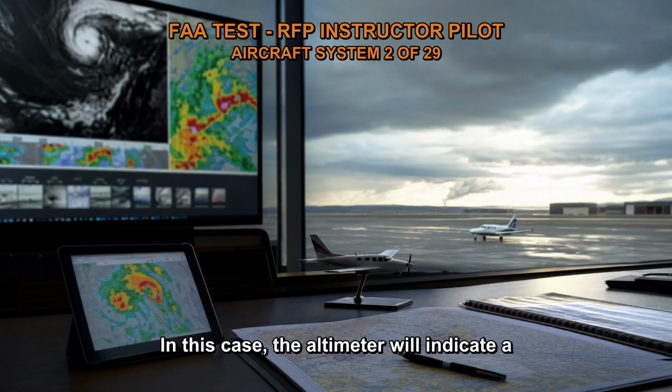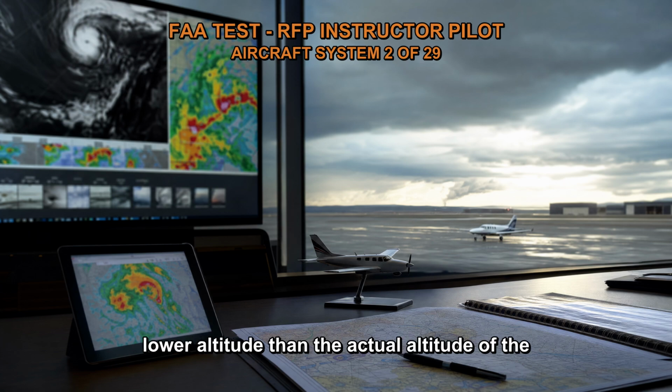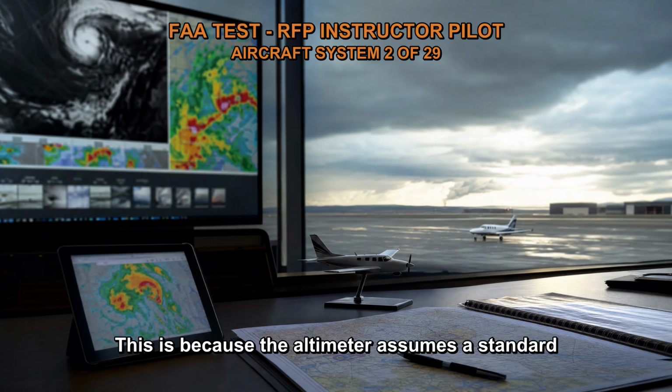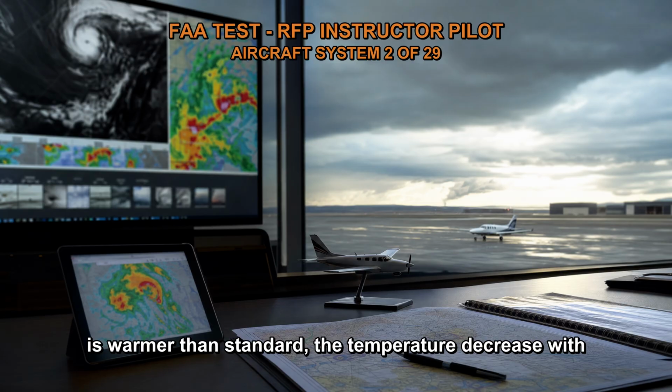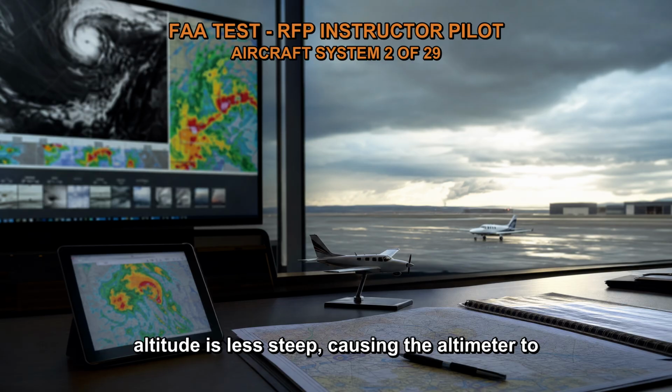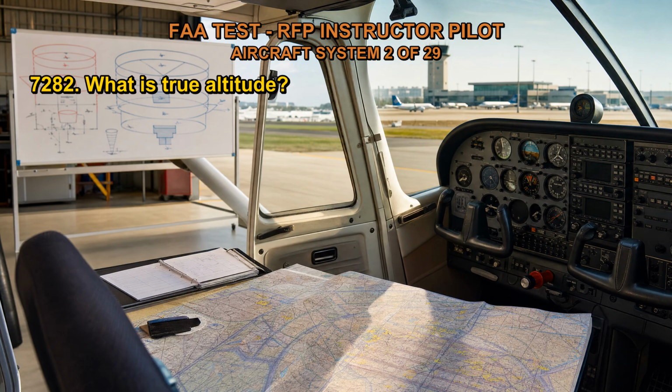In this case, the altimeter will indicate a lower altitude than the actual altitude of the aircraft. This is because the altimeter assumes a standard temperature lapse rate, and when the actual temperature is warmer than standard, the temperature decrease with altitude is less steep, causing the altimeter to underestimate the aircraft's altitude.